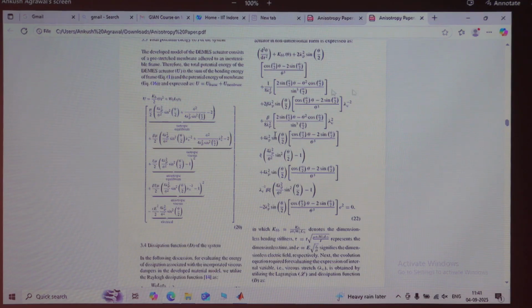What are the other parameters? Beta is a proportionality constant. What does it signify? Your spring has some shear modulus, and you are connecting the Maxwell element with the other spring. So the top spring will have some shear modulus. Now in the Maxwell element there is another spring. So the proportionality constant means your Maxwell element is ultimately going to incorporate viscosity.